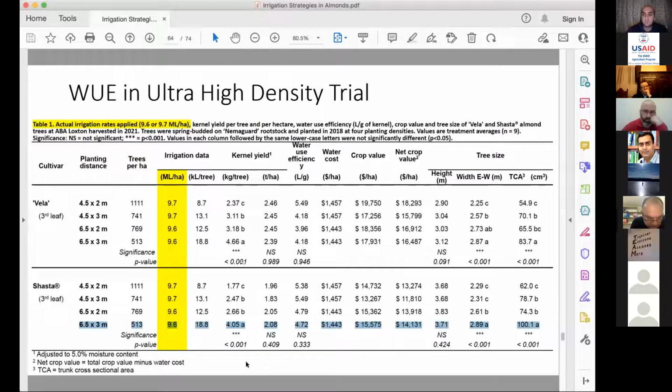It's drip irrigation. Okay. So, in California, we use sprinkler irrigation for frost protection. When it gets to lower temperatures, -1, -2, we turn the irrigation on so that we actually have a little bit of evaporative water getting into the canopy, and that helps protect the buds from frost damage.